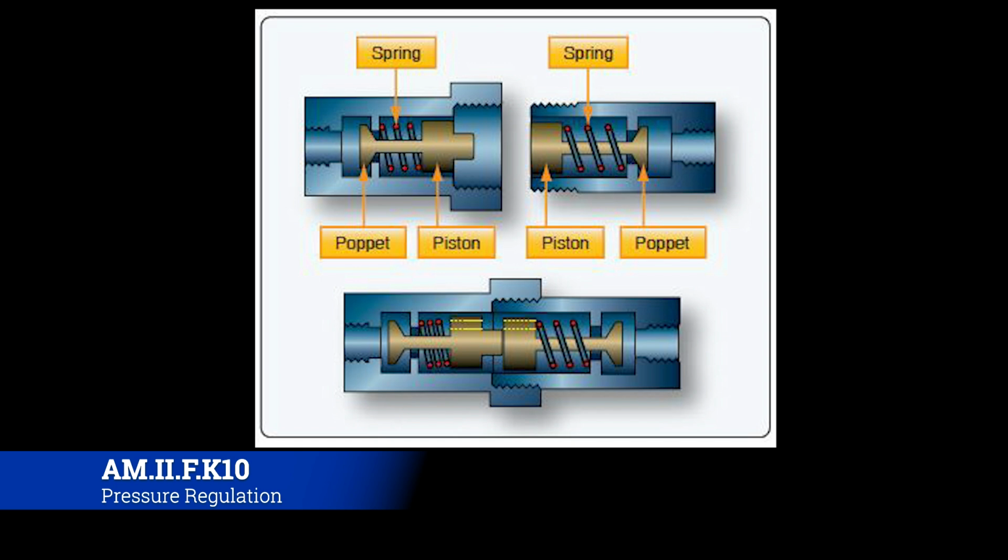The way that it attaches to the airplane is through a quick disconnect port. It allows an aviation ground power unit, like we used in the Army, or a thing called the Mule, to connect directly to the aircraft hydraulic system to provide that hydraulic pressure, so you can still actuate flight controls, swing the gear, and do all that sort of thing. Now, if you had to disconnect a line every single time and put a T fitting on, that would be pretty bad. It would greatly increase the chance of contaminating the system.